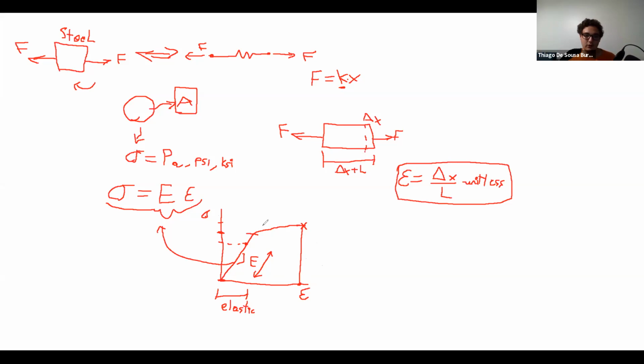So these two points are actually called the strength of the material. The elastic modulus usually represents that spring constant of the material. Once we go past that point, we go from the elastic region and enter the plastic region, and Hooke's law doesn't apply anymore. What this implies is that from this point on, our material cannot go back to its undeformed length.